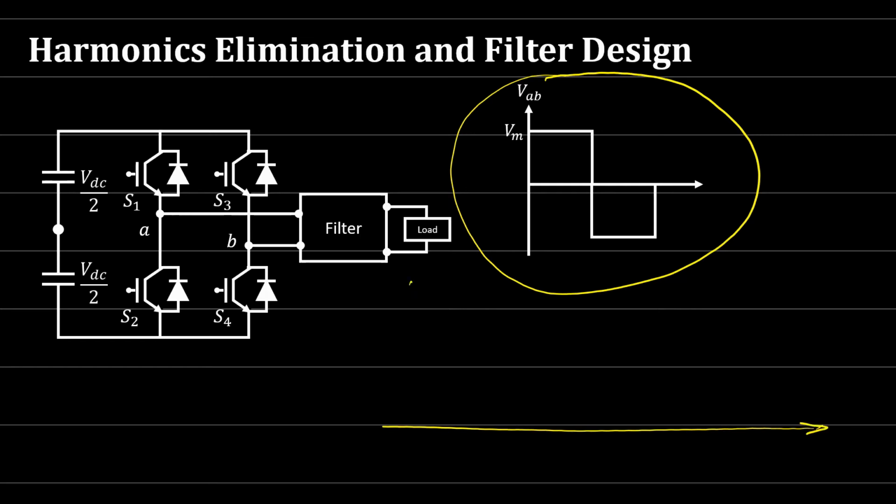Okay, if we try to draw this one, you'll find that we might have a DC component, which means the zero frequency is at some value, which is the DC component. We have the fundamental frequency, which is the 50 Hertz frequency. And of course, the even harmonics cancel each other, so we have no even harmonics. We have the third harmonic, the fifth harmonic, seventh, and so on, right?